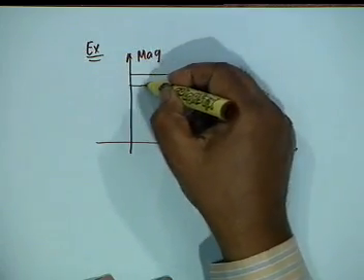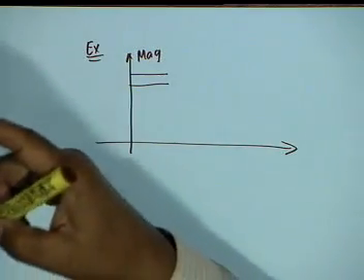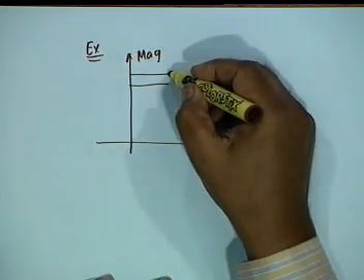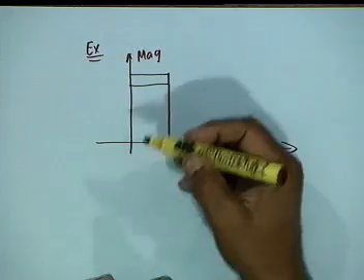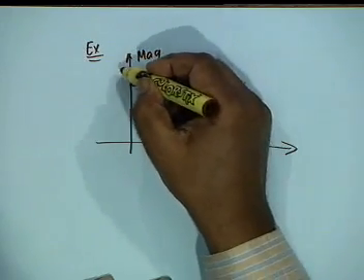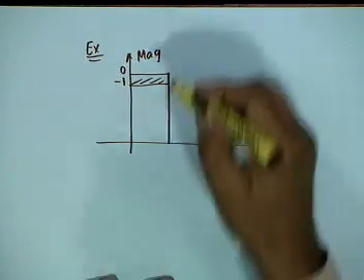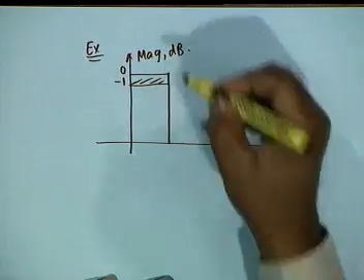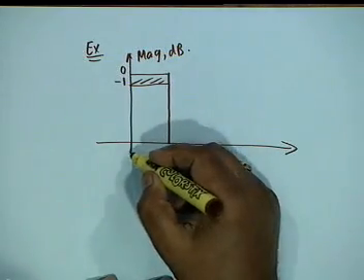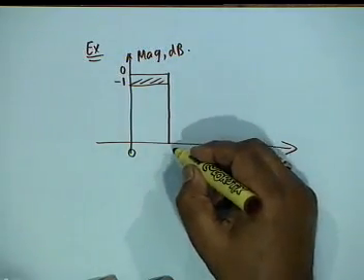In the previous case it was 1 and 0.8. Now it says 1 dB tolerance in the passband. That's pretty stiff. 1 dB tolerance in the passband, magnitude in decibel. And they said the passband extends from 0 to 2.5 kilohertz.